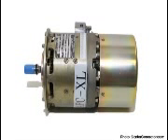The loop in position A of Figure 9.7 is rotating clockwise, but no lines of force are cut by the coil sides and no EMF is generated. The black brush is shown coming into contact with the black segment of the commutator, and the white brush is just coming into contact with the white segment.